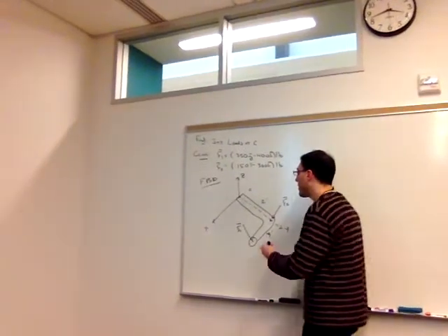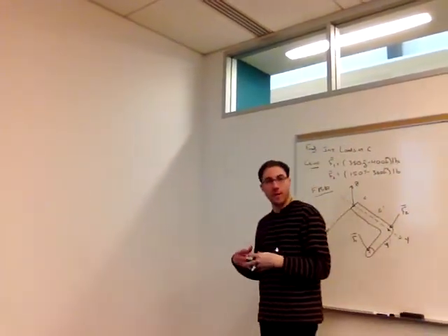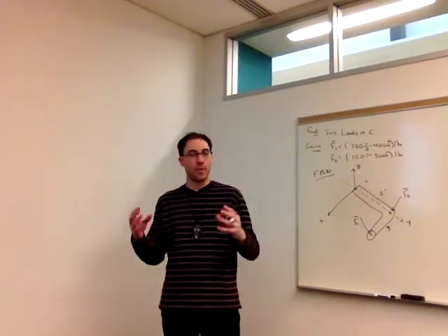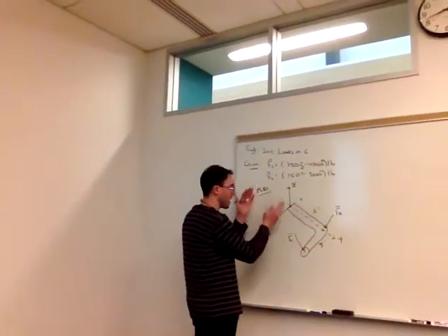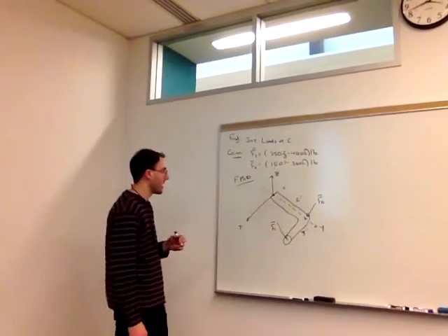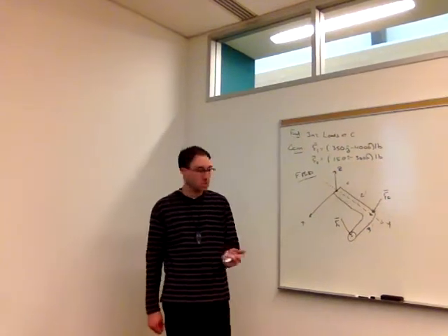Now at C, this is where I have to include the loads I can now see that were keeping the material together, that when the pipe was whole were not visible, but now that I'm detaching it from the rest of the pipe are going to come out in the picture. First thing I want to look at is the internal normal force.